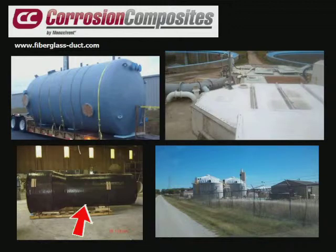The upper right-hand corner, we have some typical flat covers. And these are at the Cedar Rapids, Iowa wastewater plant. These have been in service about 5 years. They have another type of core called a Nitacore. It's a polypropylene honeycomb, and it covers all of the flat panels and makes it so that a man can walk on it, takes the 45-pound snow load, etc. Yet they stay lightweight and can be lifted off.